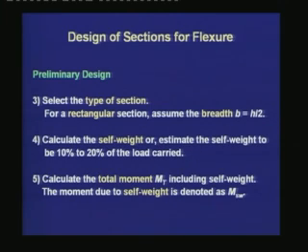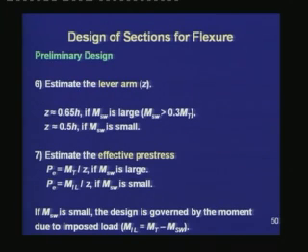Calculate the self-weight, or estimate the self-weight to be 10% to 20% of the load carried. Calculate the total moment MT including the self-weight. Here we are denoting the moment due to self-weight as MSW. Once we have estimated the total moment, which is equal to the MDL plus MSW plus MLL, we are calculating the lever arm, which is also an estimate for the preliminary design.